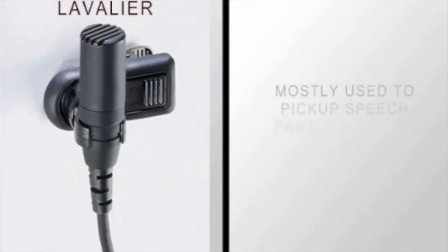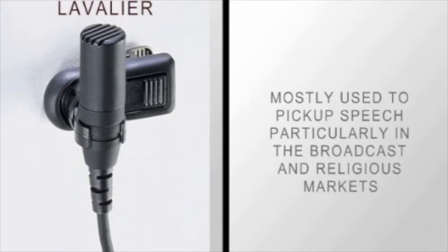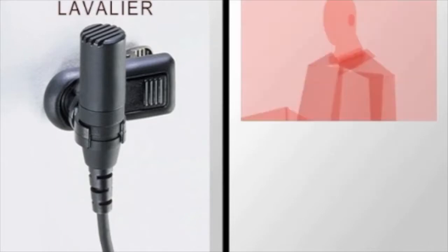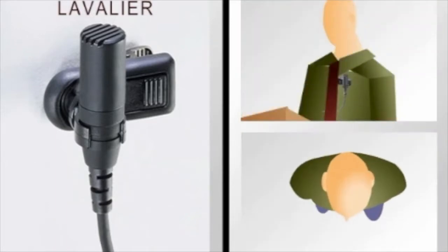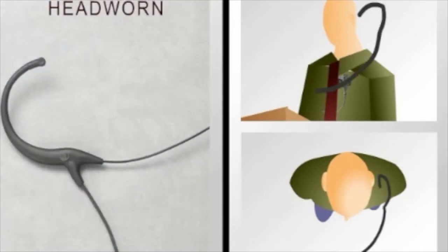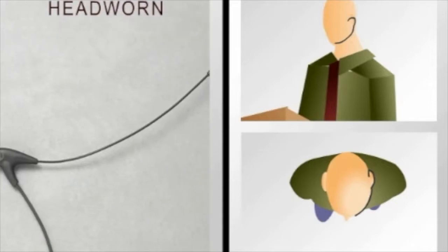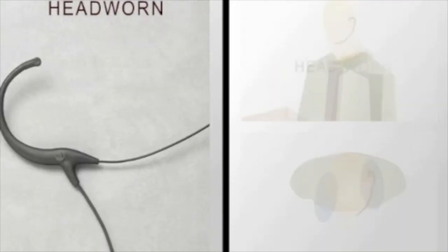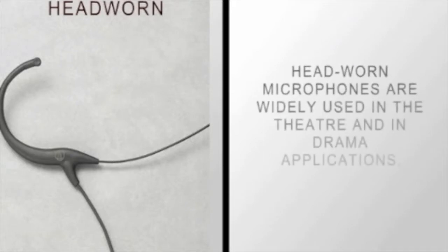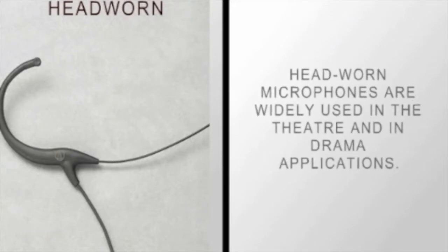Lavalier microphones are mostly used to pick up speech, particularly in the broadcast and religious markets. However, when the speaker is someone who frequently moves around and rotates their head, the lavalier microphone is often insufficient to capture all of the speech. A growing trend is the use of head-worn microphones, which move with the speaker's head and are therefore more effective than lavaliers. Head-worn microphones are typically worn over the ear and extend down the cheek of the user. Head-worn microphones are widely used in theater and drama applications.